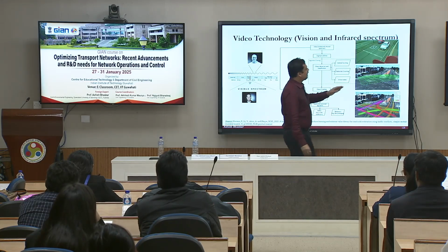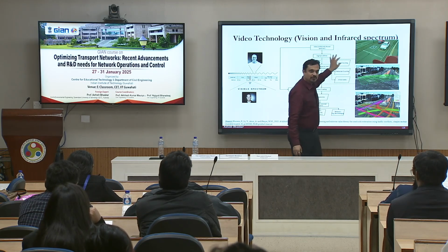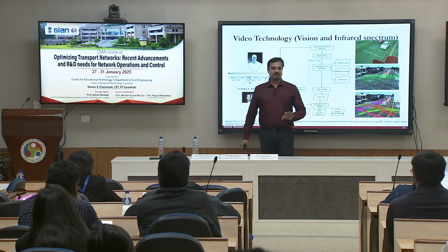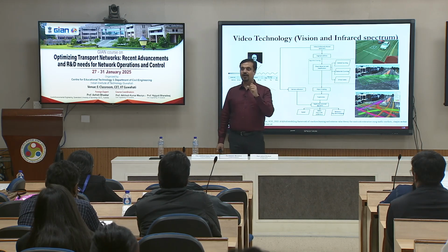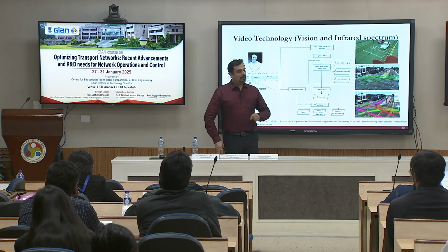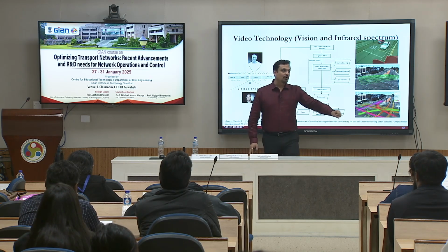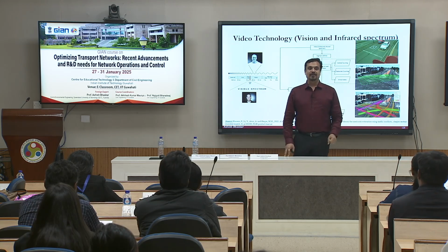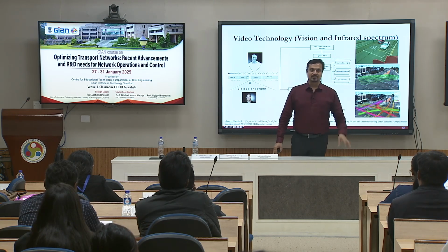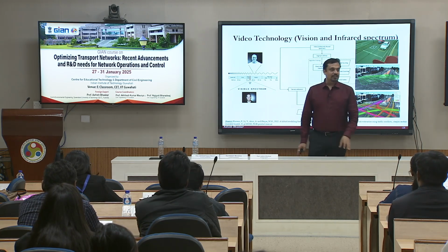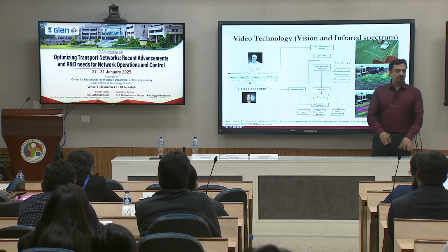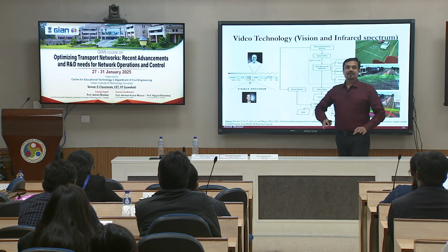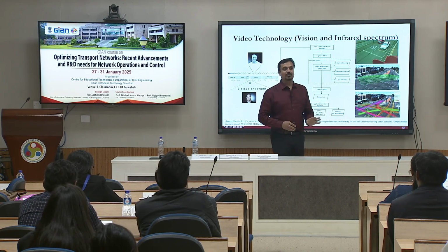If you can get the data for one intersection itself, at least you have the traffic volume pattern. You know how many road users have been served over different time intervals. So, if you have a fixed camera doing it for the last 6 months, 8 months, you have a good volume of data available to you for one intersection. If by chance you also have an upstream camera for a corridor, right. Even if you have just one, good, you can get that data set.